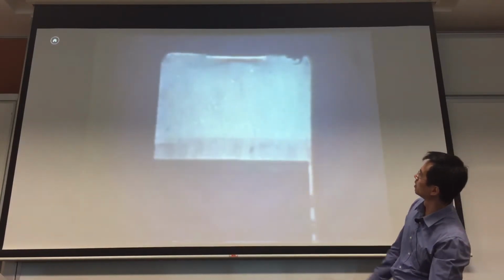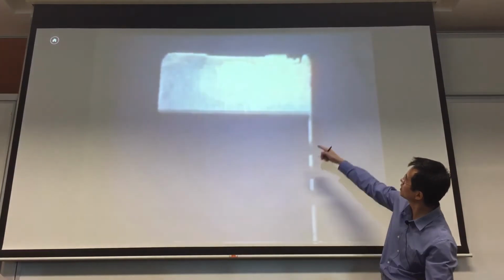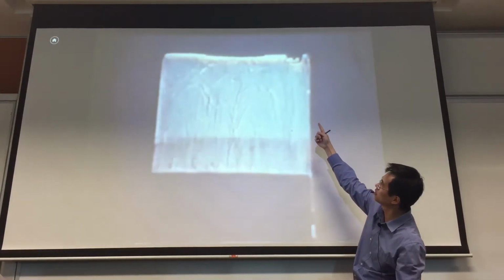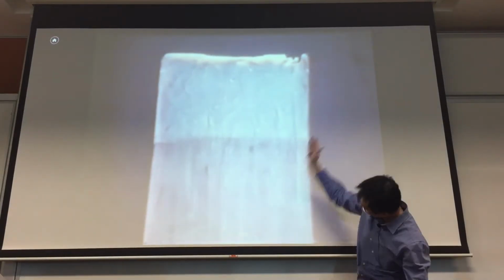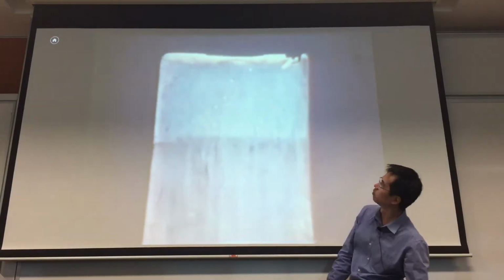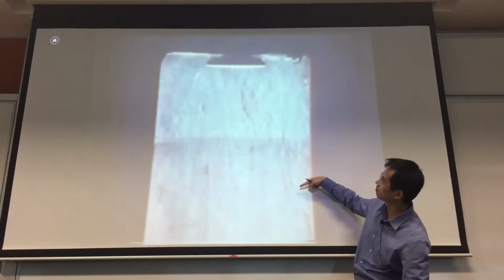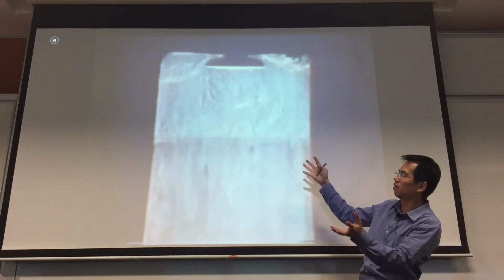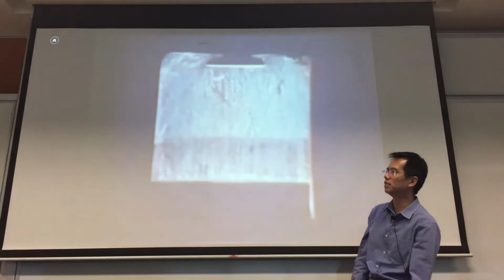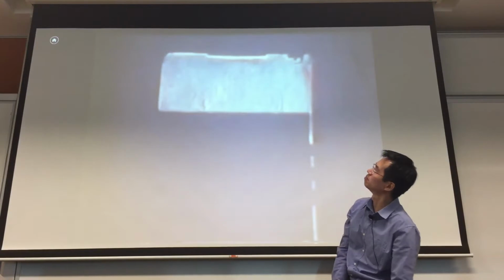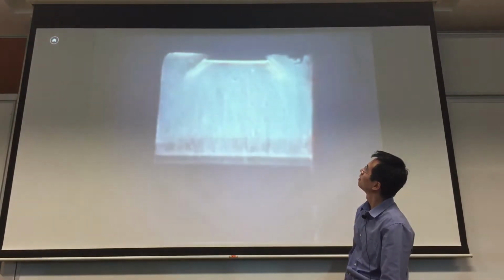So the piston is coming up. You can see that air is being compressed. It's actually a fuel that's being compressed. So the sparking is only for an instantaneous moment, and once it explodes, the piston will move to drive your car. And then now the exhaust, right? After being combusted, all the fuel will turn into mostly CO2, and that will be removed via the same valve again.